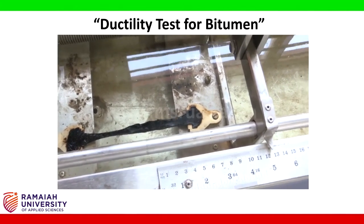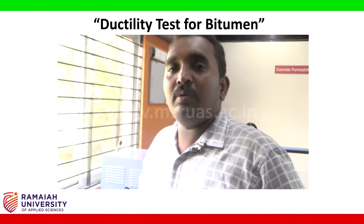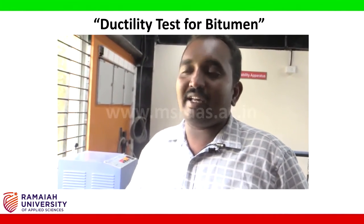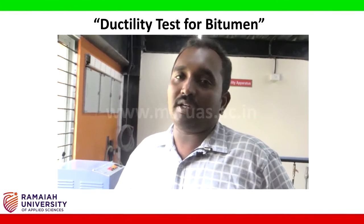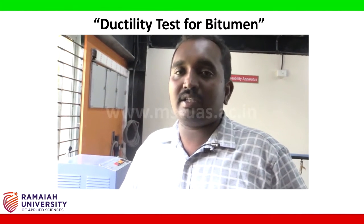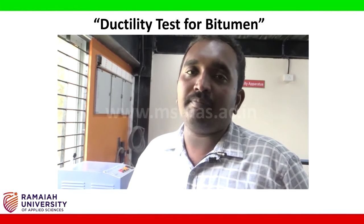In the third case, it neither fails nor expands above 100 centimeters. In this case, sagging is going to happen. Sagging means the bitumen is going to sag and touch the bottom of your ductility apparatus. Whichever the value where there is sagging and touching, that particular reading will be taken as the ductility value of the bitumen.